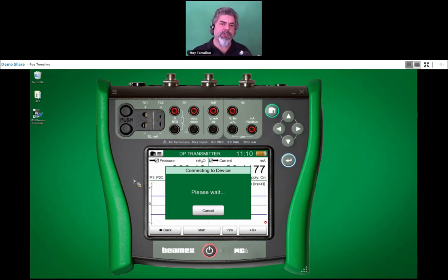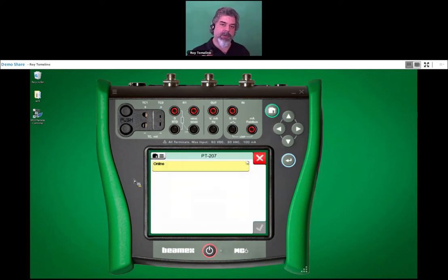The manual on the 3051 says to start at 0, so I'm going to get a head start and vent my pressure pump. I've actually tried to save time and calibrate my upper level first and then do my lower level trim, but it always seems to mess it up a little bit. So I do what the manual says, and I do my lower trim first and then the upper. All right, PT207, here we go.